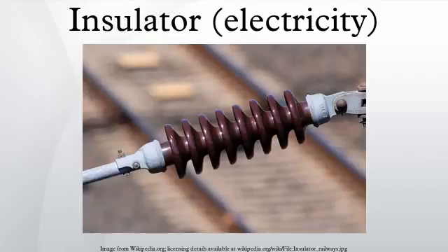Some wires have a mechanical covering with no voltage rating, for example service drop, welding, doorbell, and thermostat wire. An insulated wire or cable has a voltage rating and a maximum conductor temperature rating. It may not have an ampacity rating, since this is dependent upon the surrounding environment.